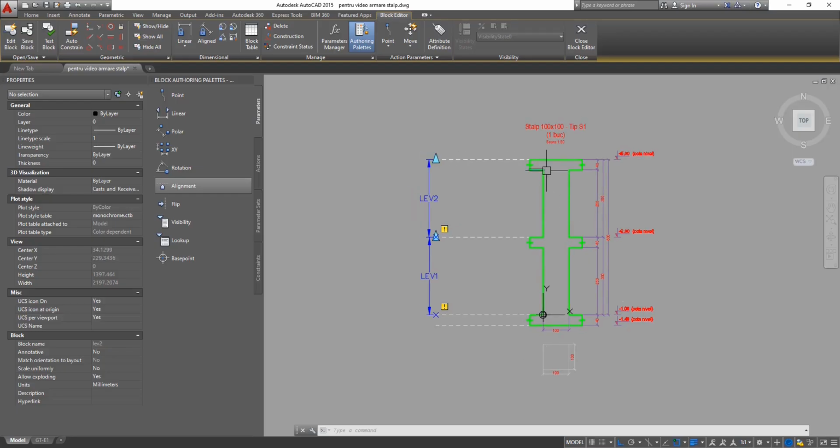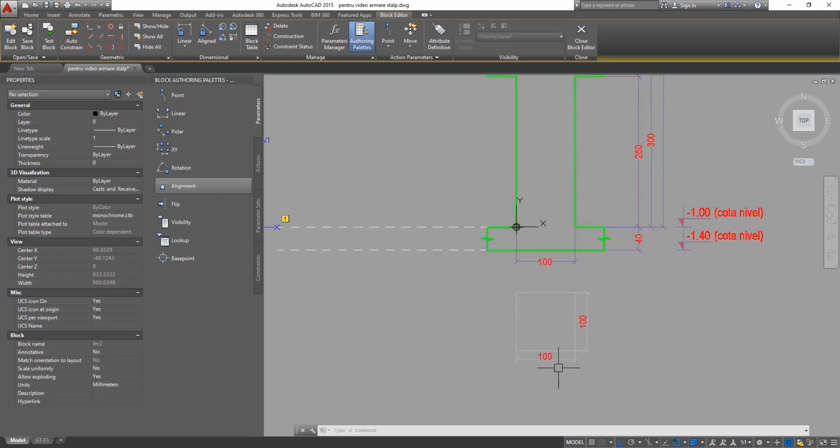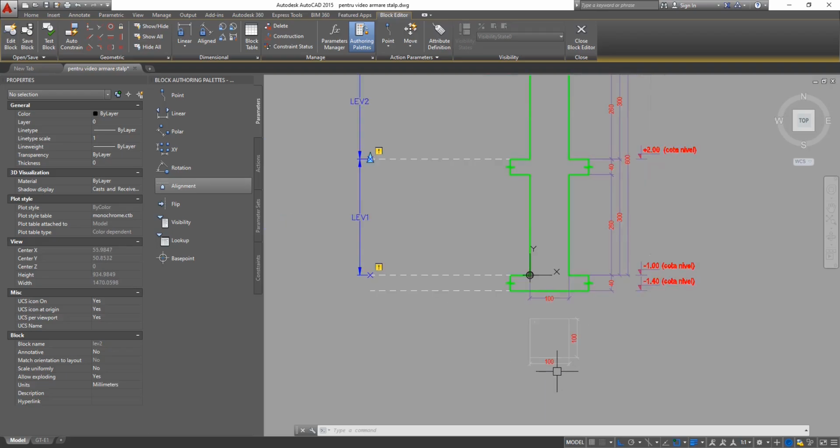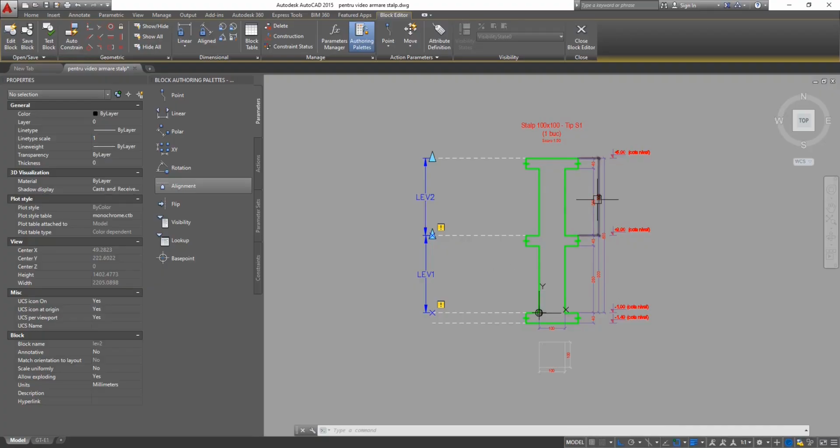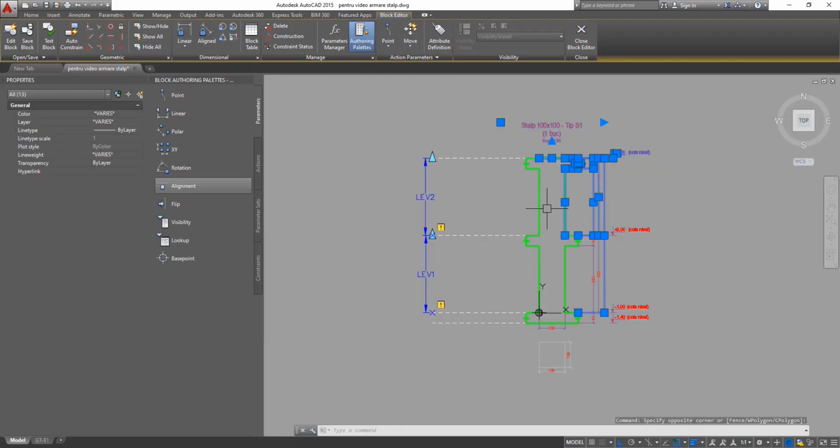Because this will be just the first step of your column. You're just going to insert an instance, and then manipulate it, reduce it to 30 centimeters. It will not be a problem. You can do it parametrically from outside. But when you are creating it, don't be cheap, okay? Just use a large drawing. Make it easy for you as a human to decide the areas you want to work with, okay?